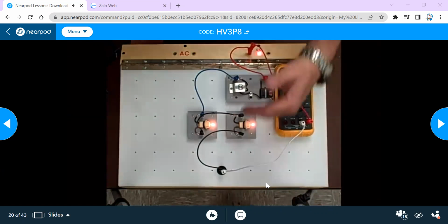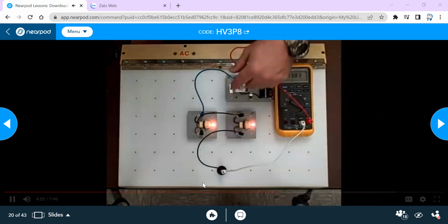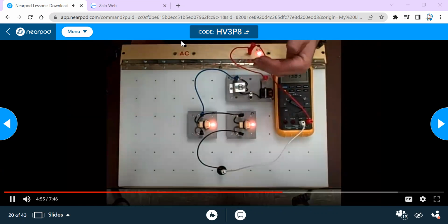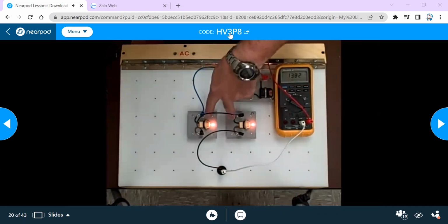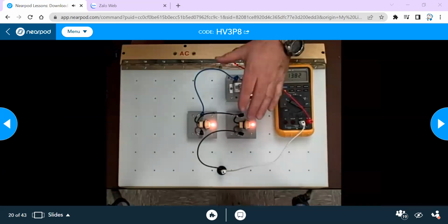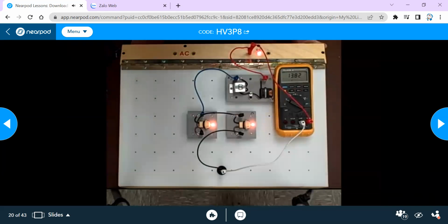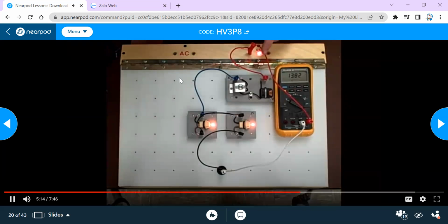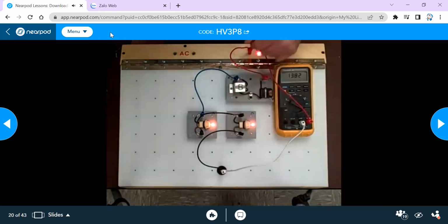And so the idea is the source voltage, the voltage applied across a circuit, will be dropped across all the loads. In this case, 2 loads. Where this happens though, sometimes you may have, say, a bad fuse holder. If it dropped a volt here, it would kind of rob that, and what's left down here would be split. So voltage drop, which we talk about a lot in these videos, is a very important diagnostic tool, a very, very powerful way to find resistance. So in a series circuit, we can add up all the voltage drops and they equal source voltage.